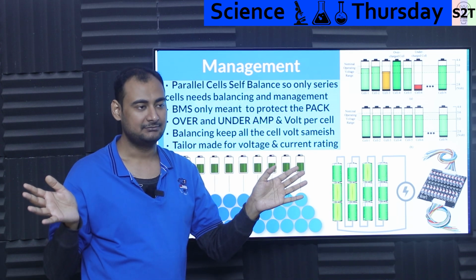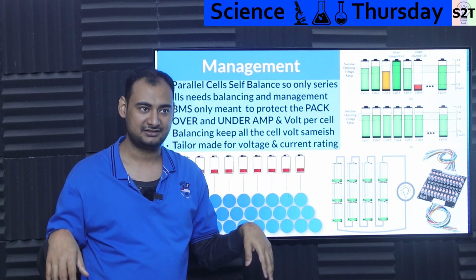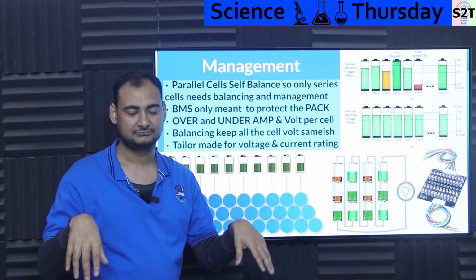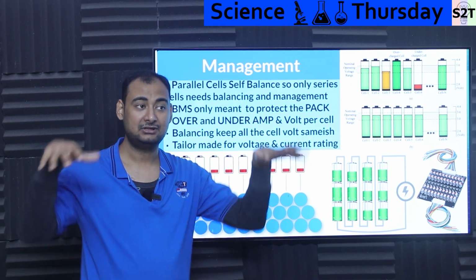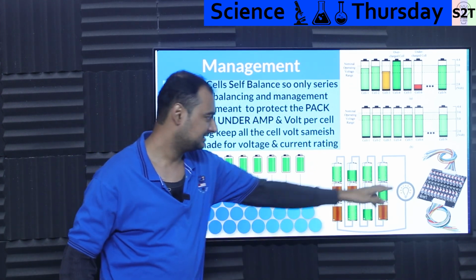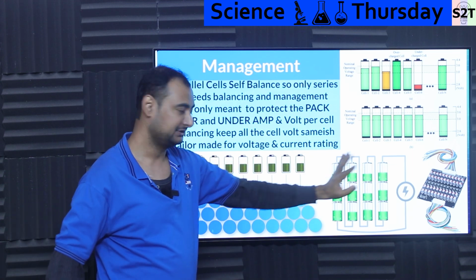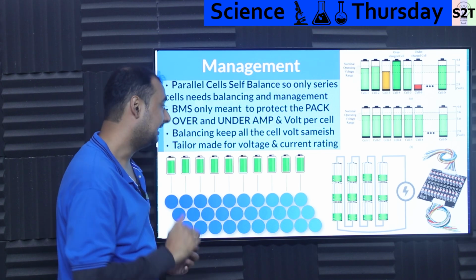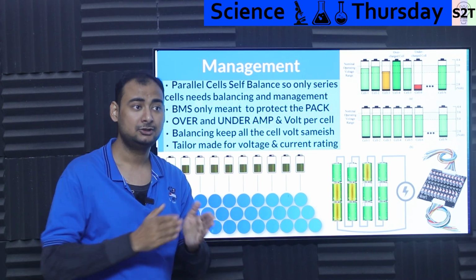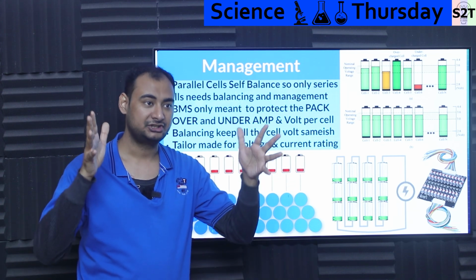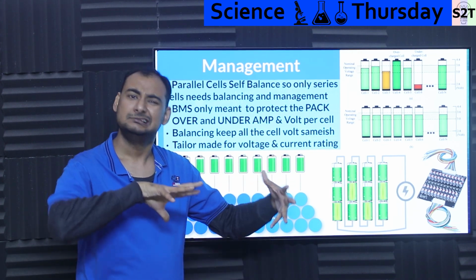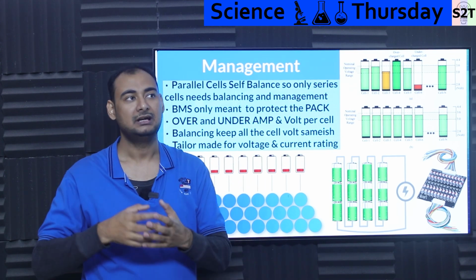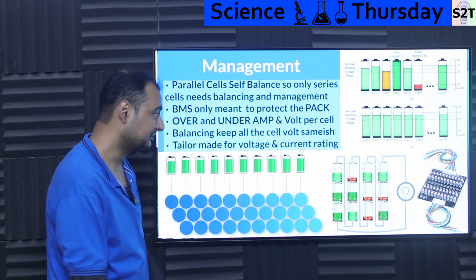So then it balances and dumps the energy. The capacitor basically dumps the energy into the weaker cell. When you series them all, it attaches to the batteries. When you parallel them, they balance it out, then dump back. Very clever. Basically, it's a very clever flip-flop mechanism. It allows all the cells to have equal enough voltage. And balancing keeps all of the cells same-ish, meaning over time you do not drift. So 100 kilowatt hour capacity remains 90 kilowatt hour useful capacity, meaning the BMS is not tripping, and it's actually useful at the 10 year point. So it's compulsory.